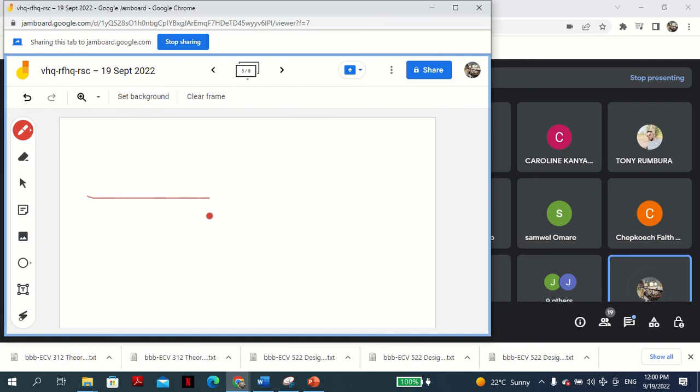So this is the initial. We are now applying the redundant, but to help us apply the redundant, you apply a moment 1 at the place of the redundant. Then you multiply the moment times the redundant. If you're a good student of structure, you realize that the moment will go up here once and then go back to 0, and that equation would simply be 1 minus x over 6.